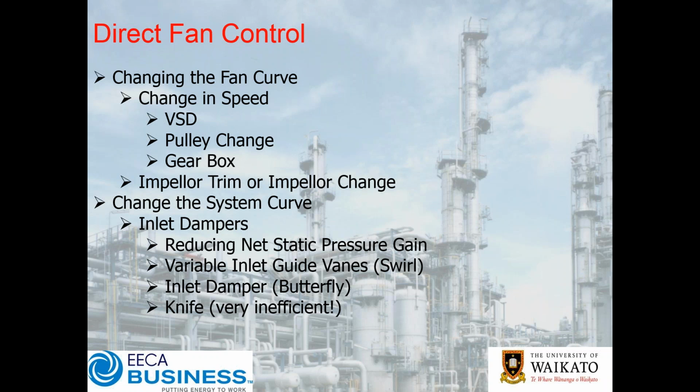So in relation to inlet dampers especially, and also applying to outlet dampers, if you've got a damper that's causing a lot of disturbance to the flow, that is certainly going to create a lot of noise. Now, depending on the nature of the system, you may decide that that's what you need, but you then may need to look at an attenuator. And so generally the good advice is to do the flow damping properly as opposed to taking a shortcut, because ultimately you'll end up having to spend more money to fix it in the case of controlling fan noise and so on. So very good comment, Graham, appreciate that.